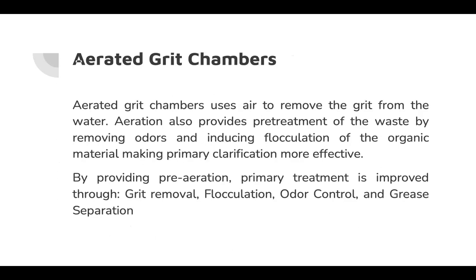So for aerated grit chambers, the aerated grit chambers use air to remove the grit from the water. Aeration also provides pre-treatment of the waste by removing odors and inducing flocculation of the organic material, making primary clarification more effective. By providing pre-aeration, primary treatment is improved through grit removal, flocculation, odor control, and grease separation.